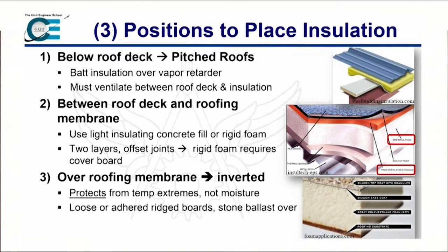The other option, that second option, is we can install it between our roof deck and our roofing membrane. So, very common in a built-up roof type scenario. So in this case, we're going to have light insulating concrete fill or rigid foam. A lot of times we're going to use rigid foam in these applications just because it can stand the heat with some sort of cover board, which we'll talk about.